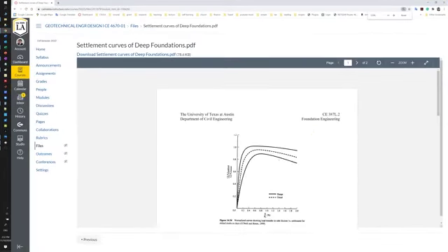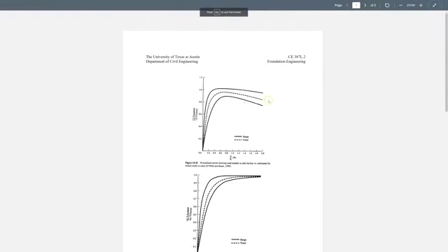So this is the TZ curve, the side friction normalized by the maximum side friction, so this is a ratio. If you have your own F max for your piles, you multiply by that number, change that to loading, and then that represents your piles.